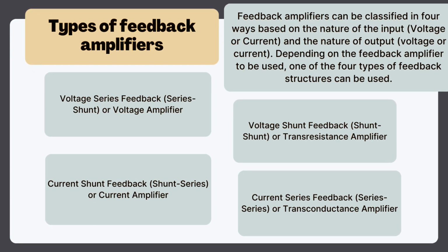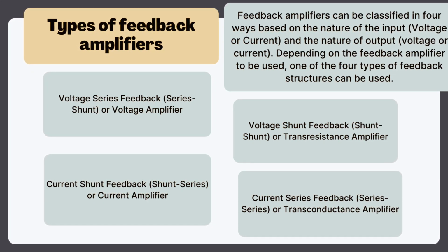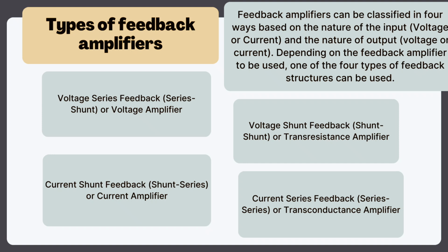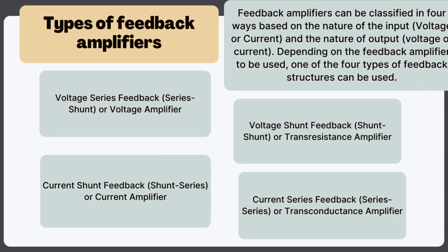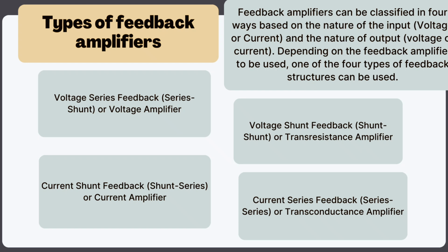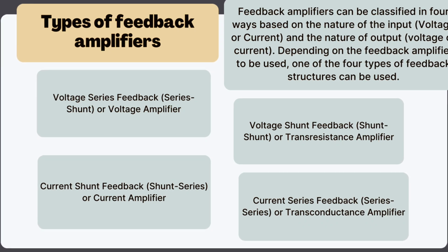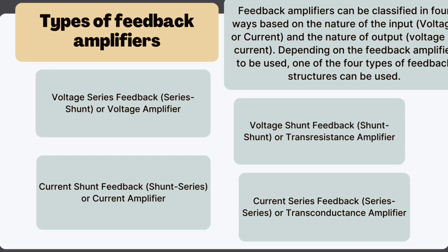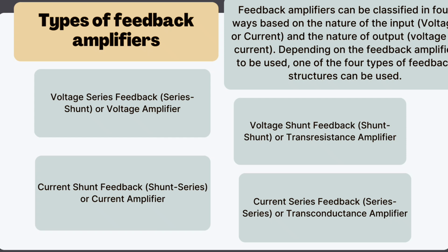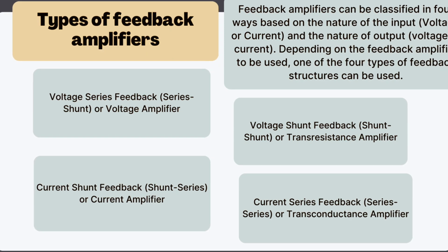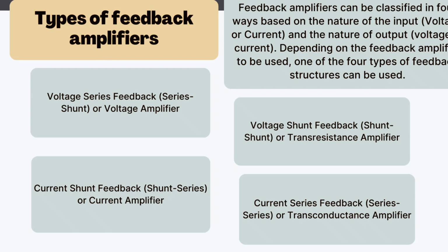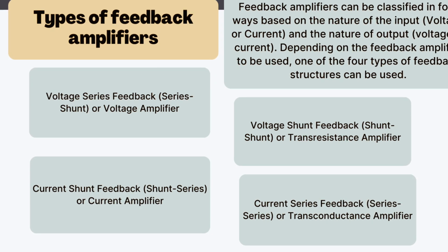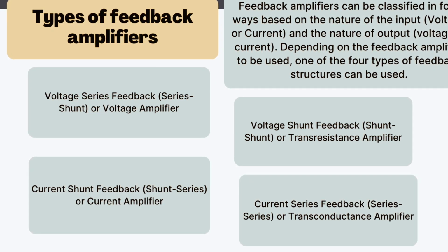1. Voltage series feedback, series shunt or voltage amplifier. 2. Current shunt feedback, shunt series or current amplifier. 3. Voltage shunt feedback, shunt shunt or transresistance amplifier. 4. Current series feedback, series series or transconductance amplifier.